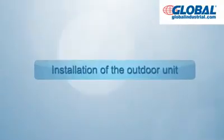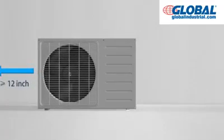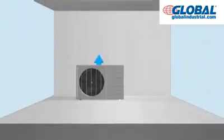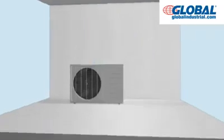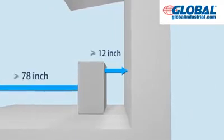Installation of the outdoor unit. Space requirement for the installation of the outdoor unit. Make sure that it is no less than 12 inches for the left space of the outdoor unit, no less than 24 inches for the right space, no less than 24 inches for the upper space, no less than 12 inches for the back space, and no less than 78 inches for the front space.